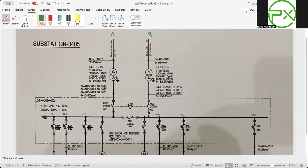They are both fed from two transformers, 11 kV to 33 kV, a step down transformer arrangement. It then contains a 415 V main LV switchboard, as we can see from QD25 here.